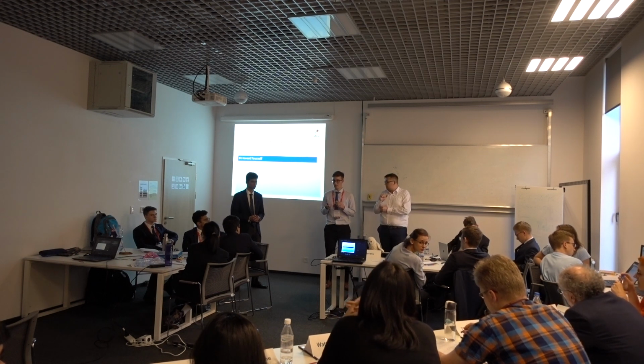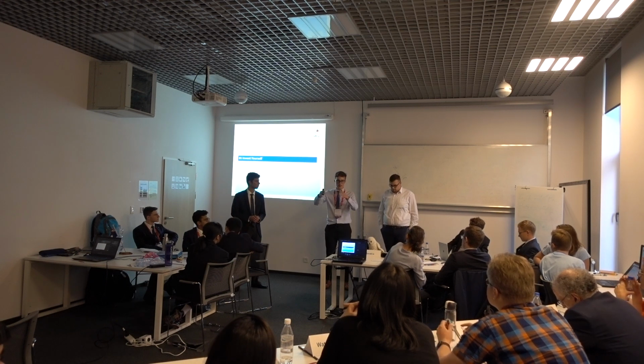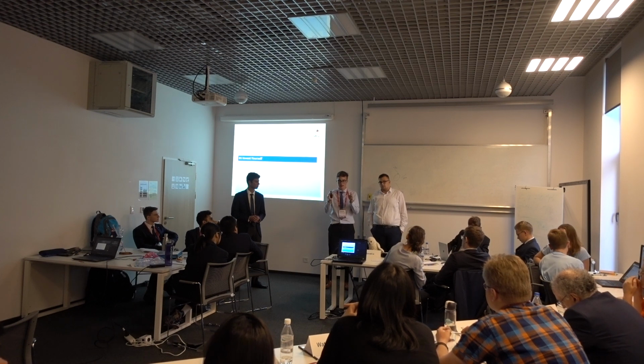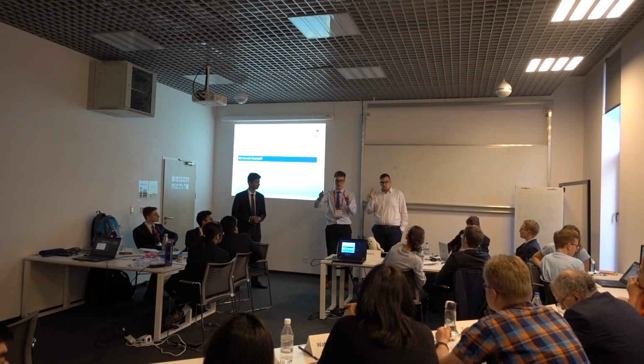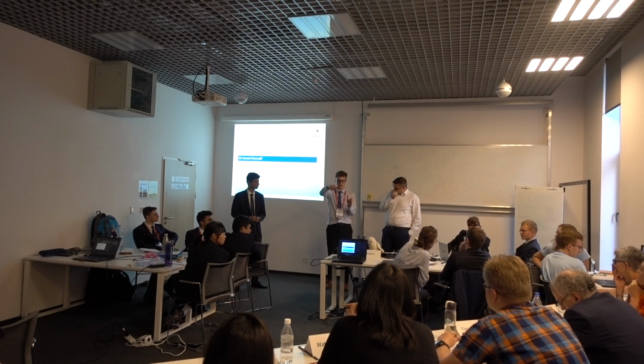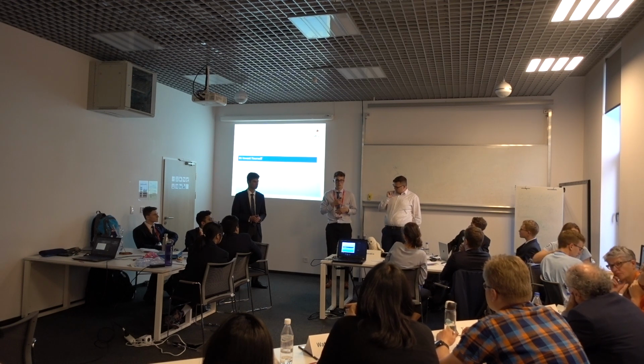So the reviewer? So in general it is indeed that when you increase the diameter you could place more electrodes around the rotor. This generates a larger torque. And to find the optimum, you just have to look at the increase of moment of inertia, and when you can keep this relatively slow compared to those electrodes, then you have increasing velocity with increasing rotor radius. Assume that you're placing more electrodes around it, because then you have a larger distance and therefore no mutual interference. Maybe someone else.